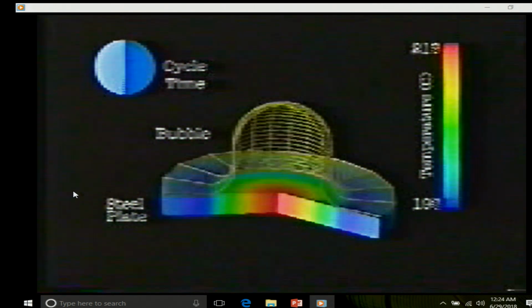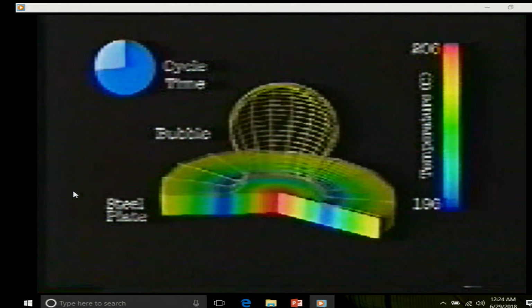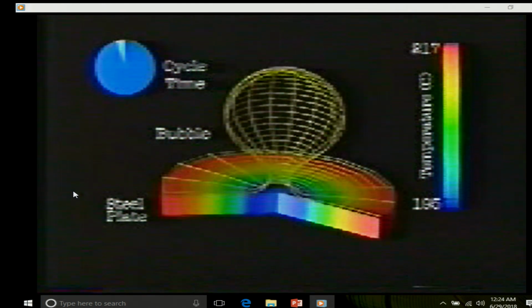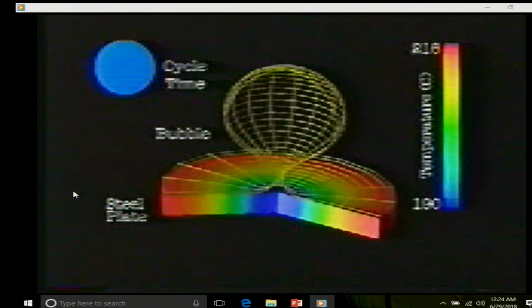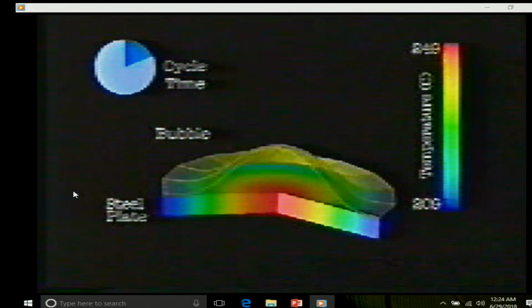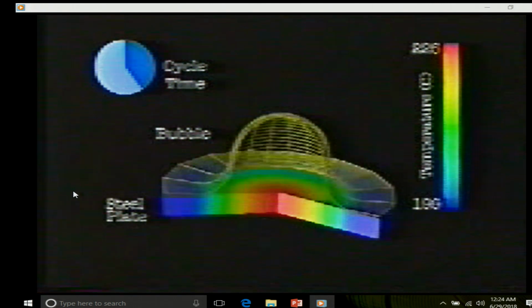But then the other big enigma is, can we go and measure this cold spot? I graduated from UCLA and went to work in the industry, but at the back of my mind I kept thinking, how do I measure this temperature, because it is very tiny. It is only about 50 microns in width and 50 microns in thickness. I cannot put a 1 millimeter diameter thermocouple in there, because that itself will serve as a nucleation spot and disrupt the whole boiling process.